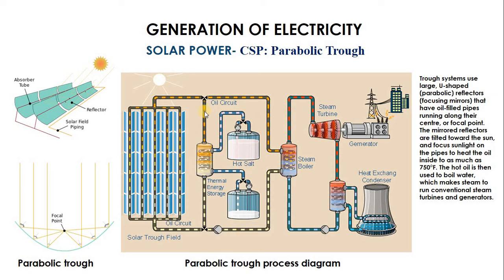And as you can see, this is still the oil cycle. So this motor will, instead of pumping the oil here, because this valve is closed, pump the oil here to fill this chamber. And because you have hot salt running from the upper tank to the lower tank, it heats up the oil that will accumulate here. So the hot oil now goes and continues doing its work.